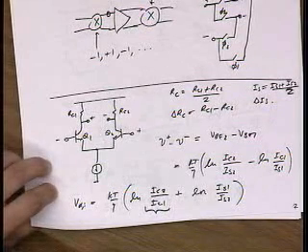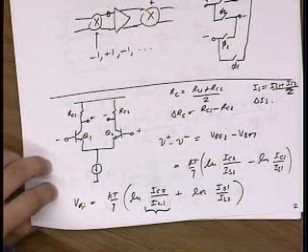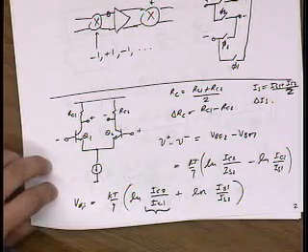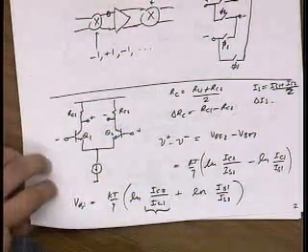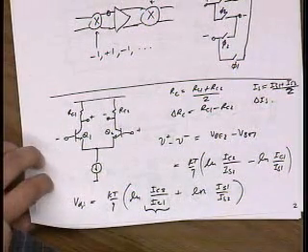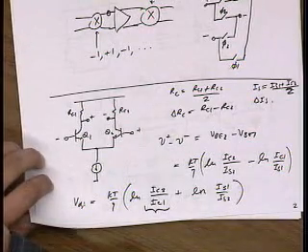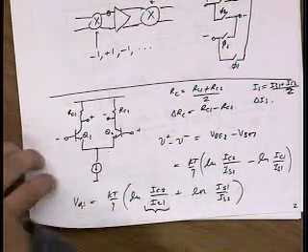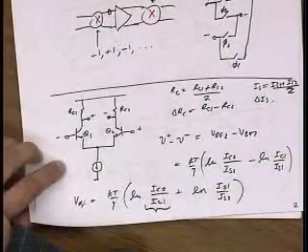What about putting a digital potentiometer in parallel with it and trimming it as you go along with some sort of feedback circuit? Yeah, that's a more modern way to do it. But again, remember, there's precision involved in your trim circuit. So what if your trim circuit has an offset voltage? So it's tricky.